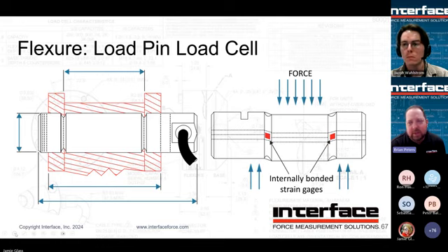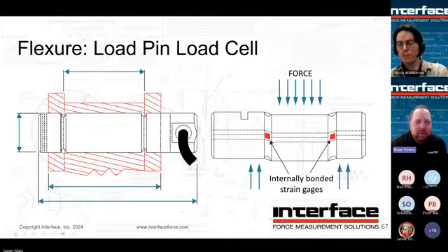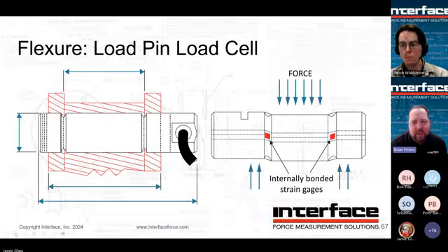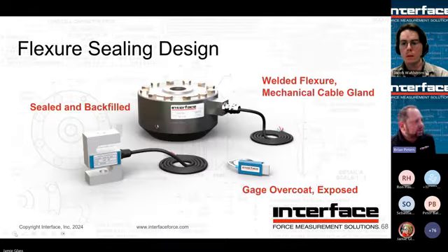same thing going on here. The gauges are going to be directly under those grooves, but that's where you want to have that double shear interface occurring from a system level standpoint. So it's really important you have tight tolerance, that you keep the pins in shear, and that you don't bend the load pins. So, all right, next.